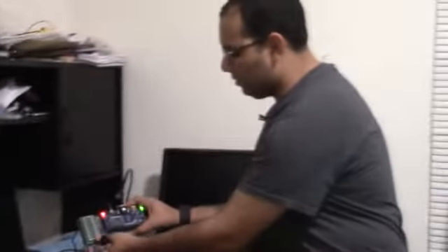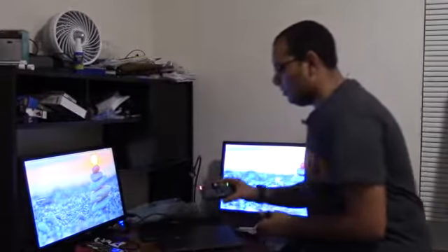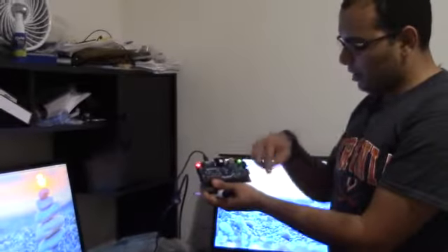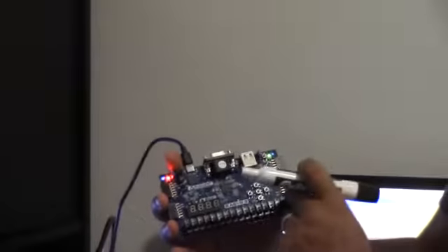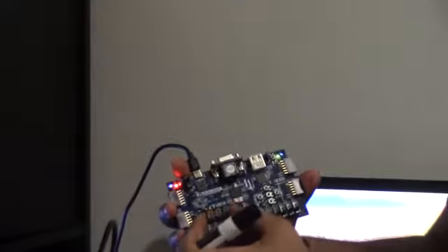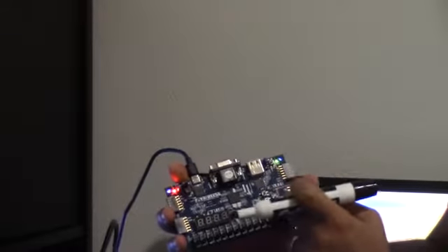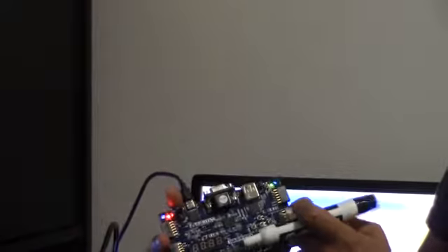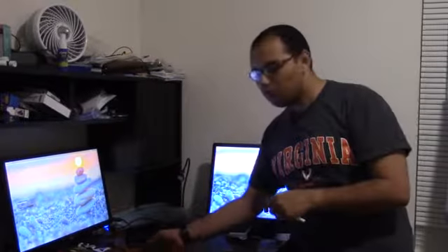If we go to the computer, I have here the board made by Digilent, and this board has different peripherals, as you can see: a set of switches that can be turned on and off, a couple of LEDs, a 7-segment display, a couple of push buttons, and PMOD. PMOD can be used for attaching different sister boards, like extension boards.